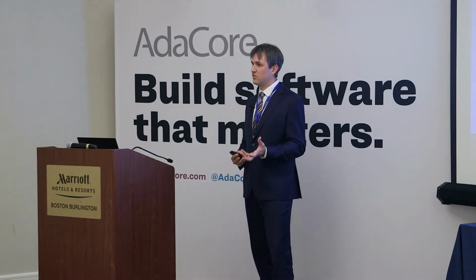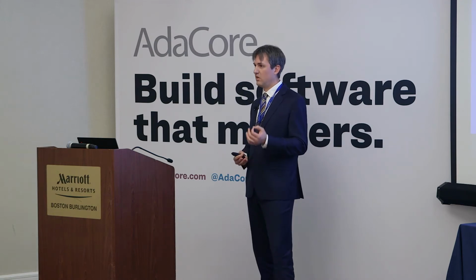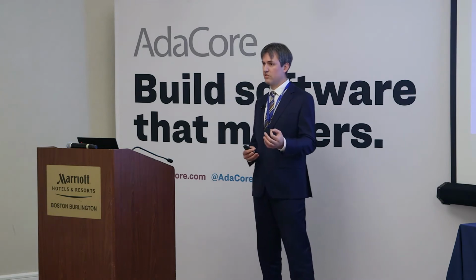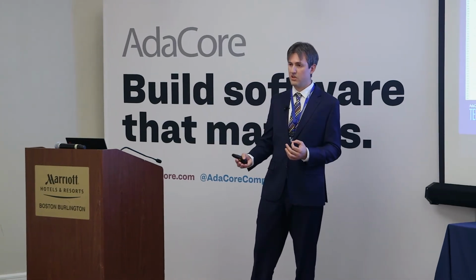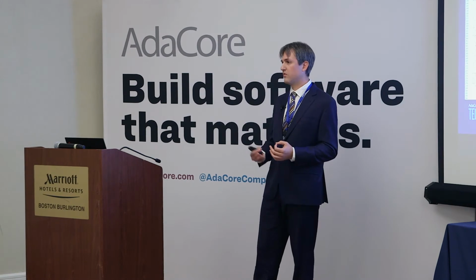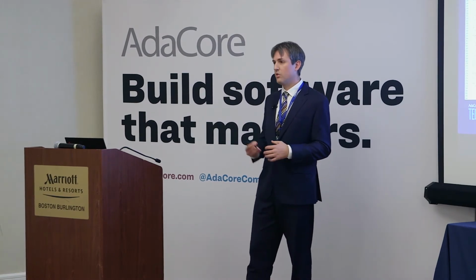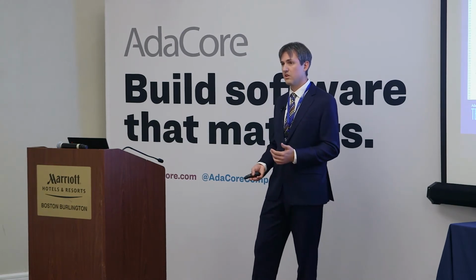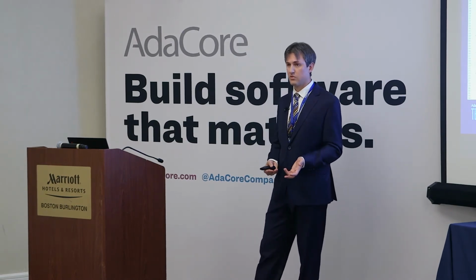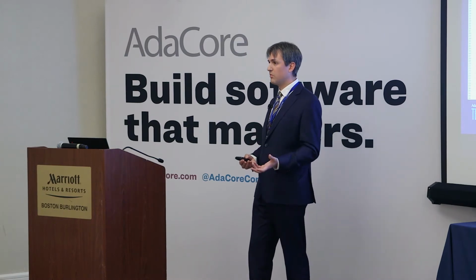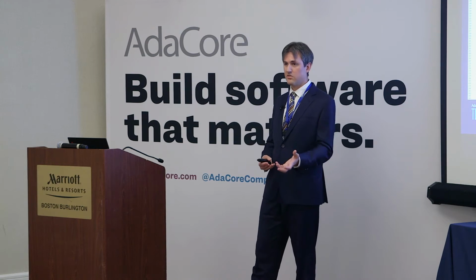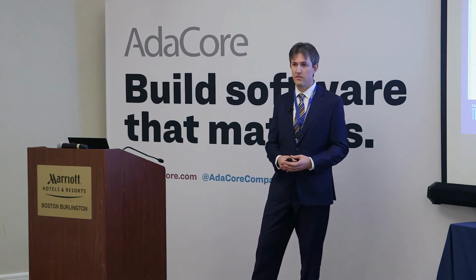One of the really nice things about QGen is you're not tied to a specific version of Simulink when you use QGen. So you have the flexibility to change your version of Simulink without changing your version of QGen. This is very important, especially if you have a qualified version of QGen. You also have the opportunity to update your version of QGen without changing your version of Simulink. This is usually not the case if you're using tools from MathWorks. So if you were using Embedded Coder, for example, you would be forced to upgrade your code generator at the same time that you upgraded Simulink and Stateflow.